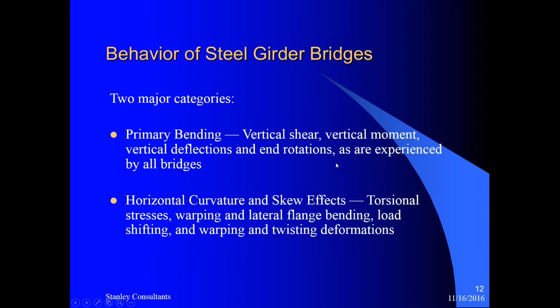In addition to that, curved steel girder bridges experience torsional stresses, which result in warping and bending of the flanges of the plate girders, and skew effects also play a role.